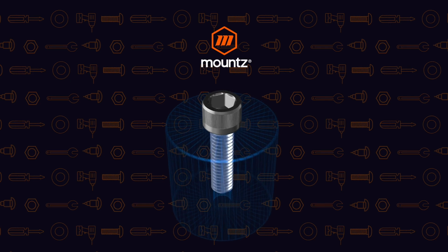Next is going to be the marking test. And so this is very simple. We simply mark the part and the fastener in a line. And then we go ahead and break the fastener away. And then we bring those two lines back together and we see what that value is.